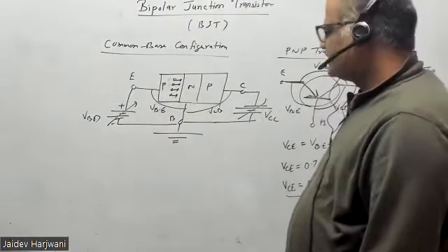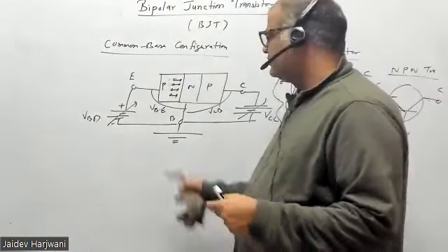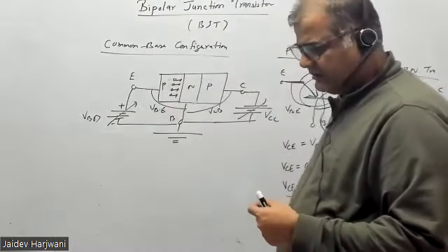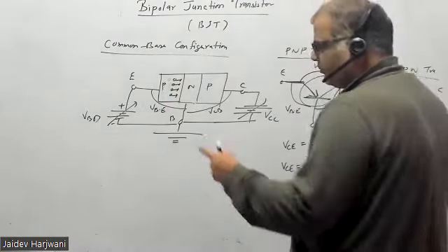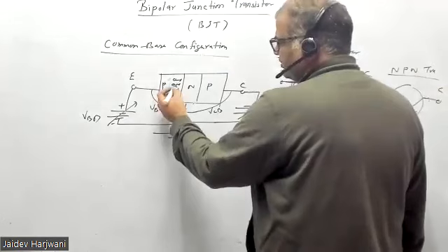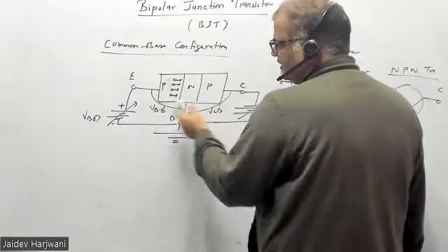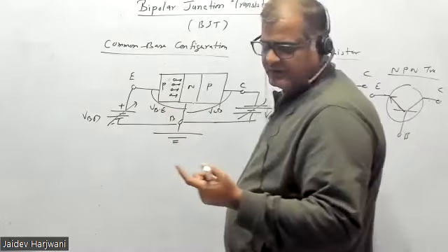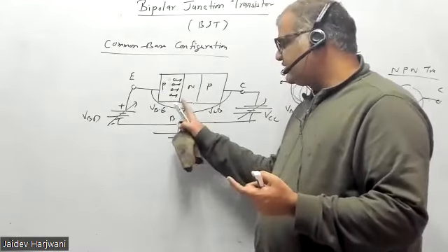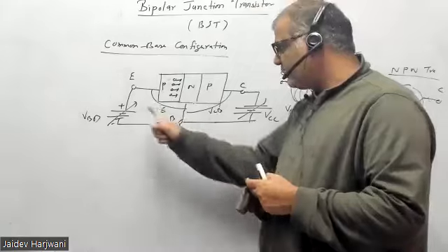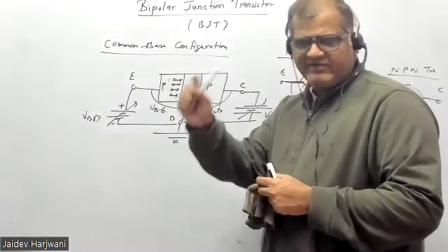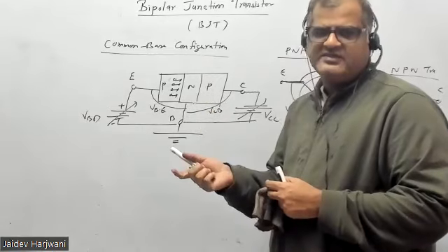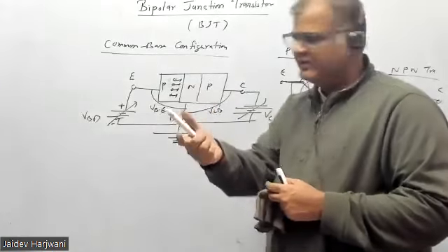That means you're pushing these holes, okay. Exact operation, you are pulling the electrons. Pulling the electrons is the same as repelling the holes. So when you're applying forward bias, these holes get injected, okay. Why inject? How does injection happen? By diffusion, okay. So there is a junction, there is a barrier. As you apply forward bias, this barrier width will decrease, and I told you whenever barrier width decreases, that means you are opening the gate, okay.